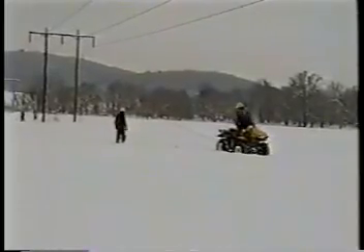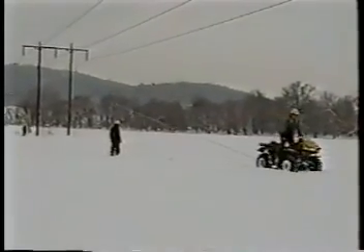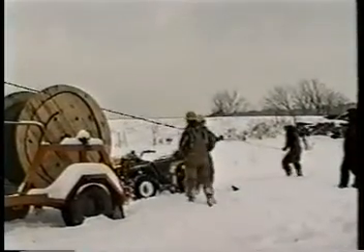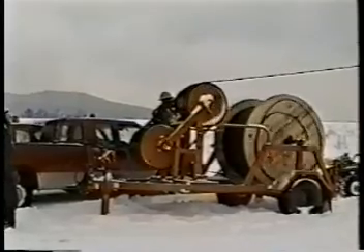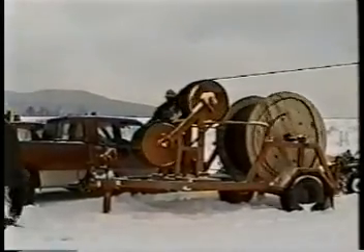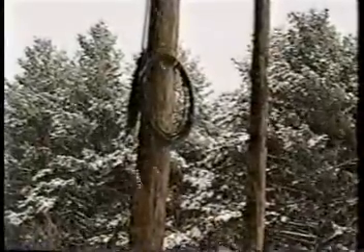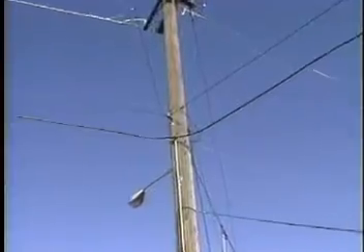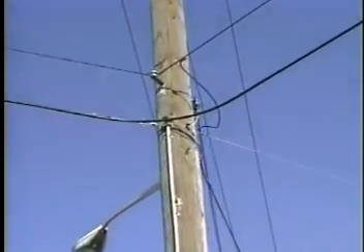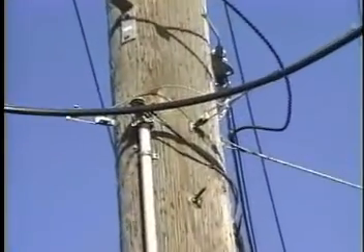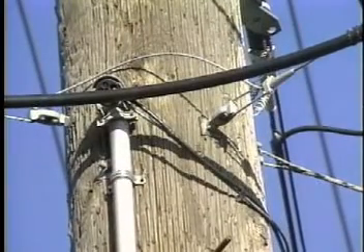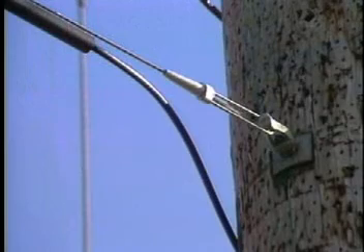A small pulling line is then run through the travelers at each aerial structure and attached through a swivel to the cable. The cable is then pulled through the section while carefully monitoring pulling tension. At the end of the cable reel or the end of the route, enough slack is left for splicing. The messenger or cable must be dead-ended at the start of the cable run or where direction changes are made. Dead ends are available in a number of styles, from bolted clamping devices to automatic compression types.